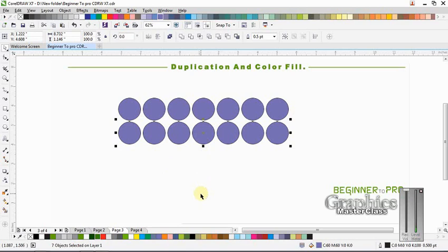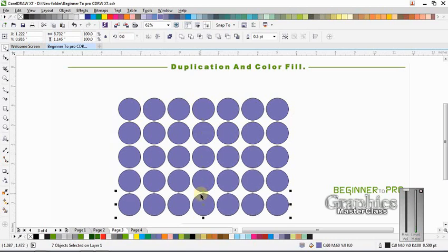Let's try it out. It's a wonderful tool to use most of the time. It makes your work efficient, especially when you're working around people, so they can see you as a pro using this technique right now. Alright, that's some of the ways you can use your duplicate: the default duplicate offset, the smart duplicate, and the Control key duplicate. Don't forget your Control D for duplicate, and hold down the Control key for your duplicate constraint.